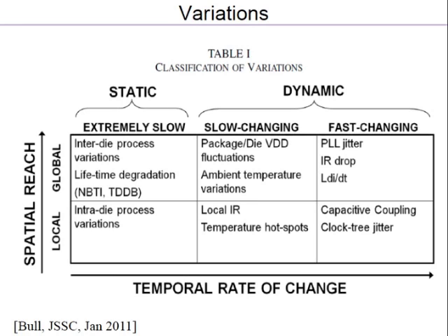Whenever you have a charge in the oxide, above the channel, it changes the threshold voltage. The charges could be mobile charges which slowly move with time. Positive charges embedded: over time, if you keep on applying a negative gate voltage for a PMOS, it will slowly start pulling that charge, and it will cause a shift in the threshold, so the threshold slowly changes with time.